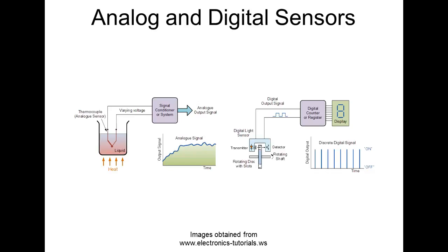But what we have the ability to do is take an analog sensor and run it into what we call an A to D converter. So when you say I want my temperature to maintain 70 degrees, then what it's doing is setting the threshold of an analog to digital converter. So when my temperature gets to that temperature, it either cuts on my air conditioner or cuts on my heater. So you've got a perfect example of an analog sensor working in a digital world, right? So a thermostat is a really good example.